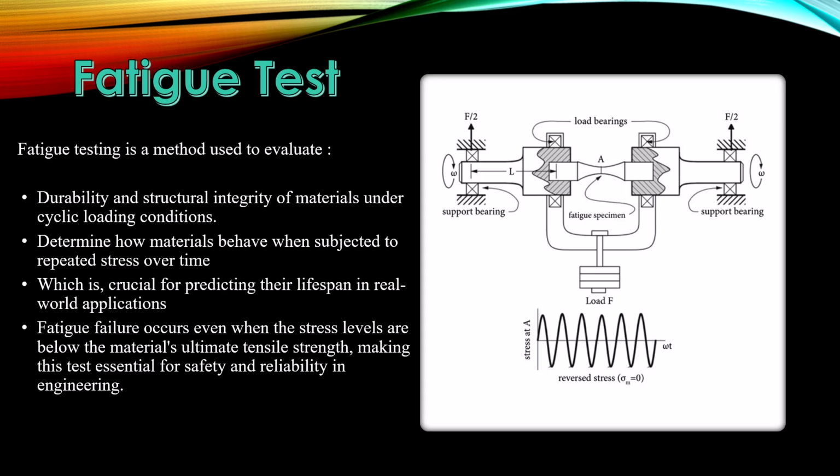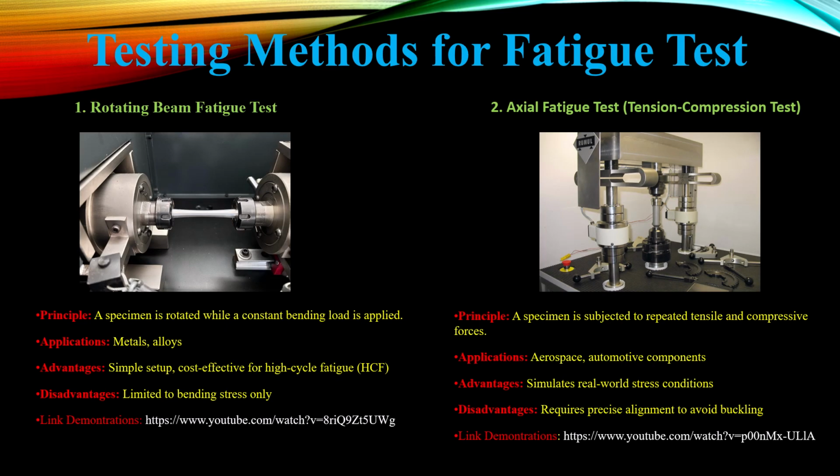Now is the time for us to understand about fatigue tests. Fatigue testing is a method used to evaluate the durability and structural integrity of material under cyclic loading conditions. Fatigue tests also determine how material behaves when subjected to repeated stress over time, which is crucial for predicting their lifespan in real-world applications. Fatigue failure occurs even when the stress levels are below the material's ultimate tensile strength, making this test essential for safety and reliability in engineering.